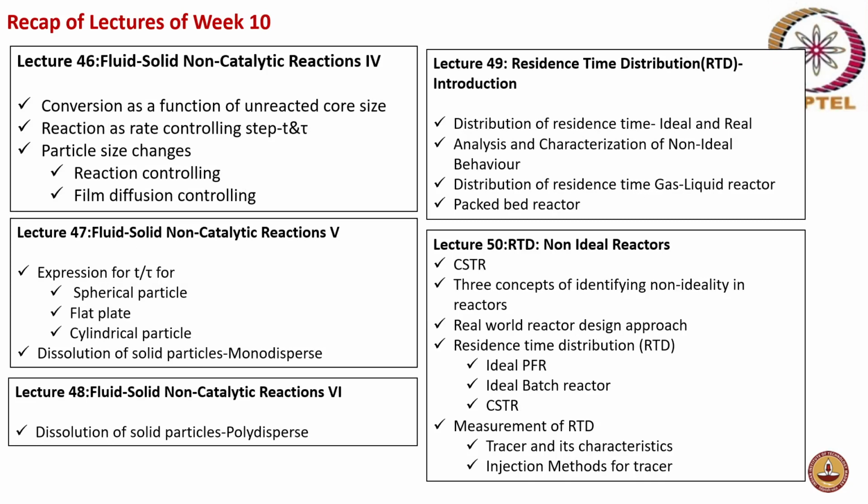Week 10 lectures included further continuation on fluid solid non-catalytic reaction, where discussion on when reaction is rate controlling for a shrinking core model where the particle size does not change, and also when particle size changes, what is an expression for when the reaction is rate controlling and when film diffusion is rate controlling were discussed. And expression for t by tau for a spherical particle, flat plate, cylindrical particle was discussed.